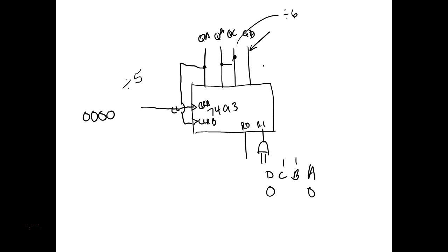So the 7490 is a divide by 10 if we don't change the modulus, right? You understand? The 7492, which we don't do any alterations on, is a divide by 12. And why they do that, guys, I don't have the slightest idea. There's not even a base 12 that we would count in, right? You understand that? In a 7493. So what are the 2 categories of counters? BCD and binary.